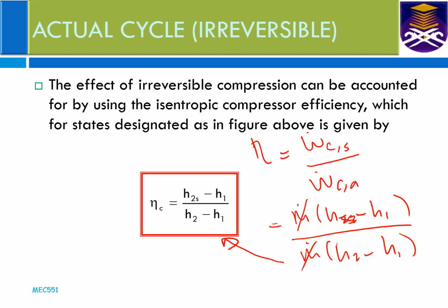Okay, so usually the compressor efficiency ranges from about 70 to 80%. It depends on the design itself. So this is the common range for a compressor. But as the compressor runs over the years of operation, its efficiency will be reduced due to several problems.